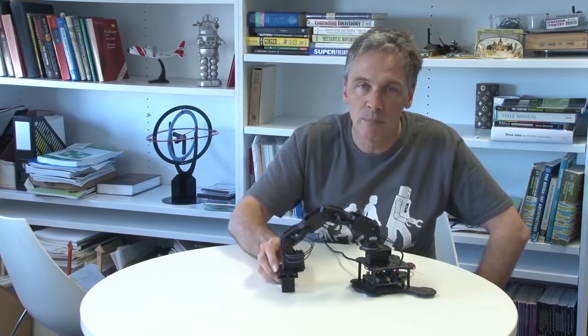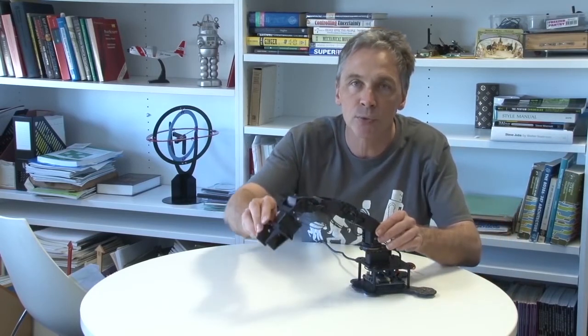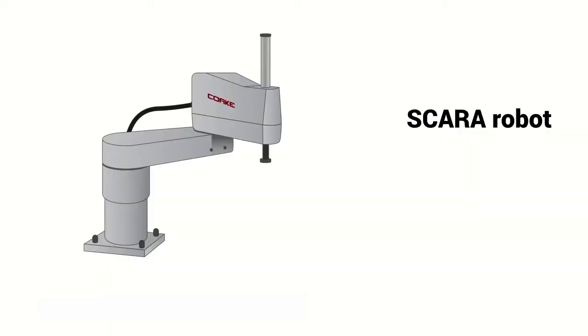The robots that we've looked at so far move in the 2D plane, but most useful robots move in 3 dimensions. What we want to do now is to determine the pose of the end effector of this robot, which moves in 3-dimensional space. The process we follow is very similar to the process we did for the 2-dimensional robots. First of all, we introduce a reference coordinate frame, and then we indicate the part of the robot, the object, whose pose we're interested in. That's the end effector of the robot, indicated here by the symbol xi.